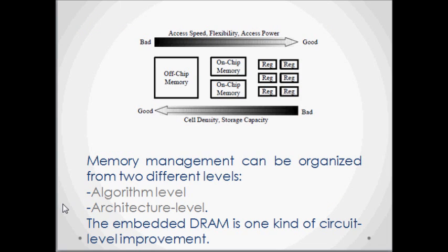Off-chip memory, usually DRAM, offers a large amount of storage size but consumes the most power. The off-chip memory and I/O access may dominate the power budget. The embedded DRAM is developed to reduce I/O access by integrating large on-chip DRAM. However, the embedded DRAM has many physical design challenges that still need to be solved. Besides, embedded compression techniques can be applied to reduce the off-chip memory bandwidth and size for video codec design.